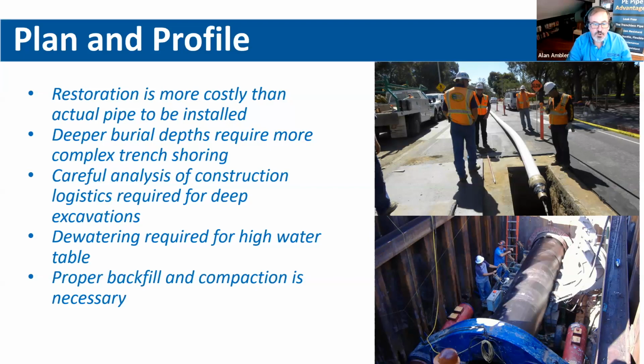Absolutely. One of the things that we show here is definitely in deep excavation, since we get technical logistical questions about it. But if you don't have that deep of an excavation and you can afford to not have somebody in the trench, we now can take full advantage of that long continuously fused pipe as we go through and be able to maximize our productivity.